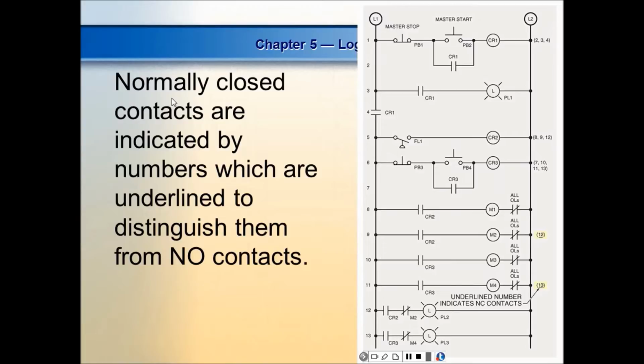It's a relay. A relay has contacts. Nobody can take a guess? Yeah, right here, I come down here and I hit this relay. So there's a relay right there. In fact, it's a motor starter. How do I know it's a motor starter? It's got overloads out there. So this is a motor starter.